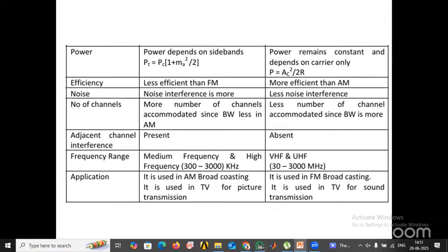In the direct method, the input is applied to a voltage controlled oscillator, where the output frequency of the oscillator is changed according to the voltage supplied at the input. For that, a varactor diode in series with an LC generator can be used. In the indirect method, first we generate narrowband FM and then pass it through a frequency multiplier, to get wideband FM. That is the indirect method. By using the direct method, narrowband FM is generated. By using the indirect method, wideband FM will be generated.